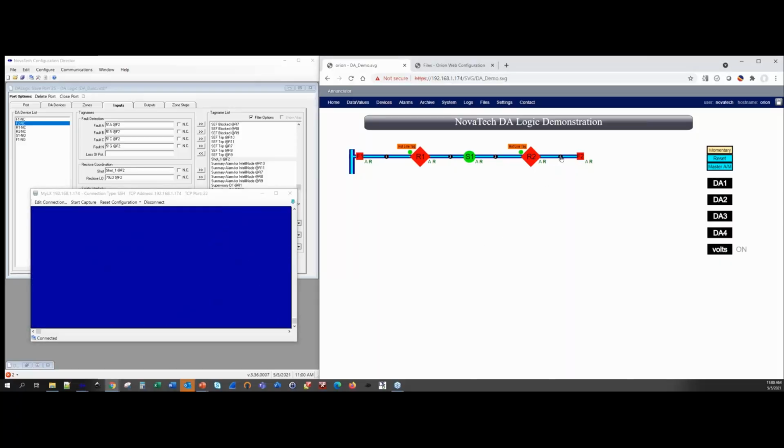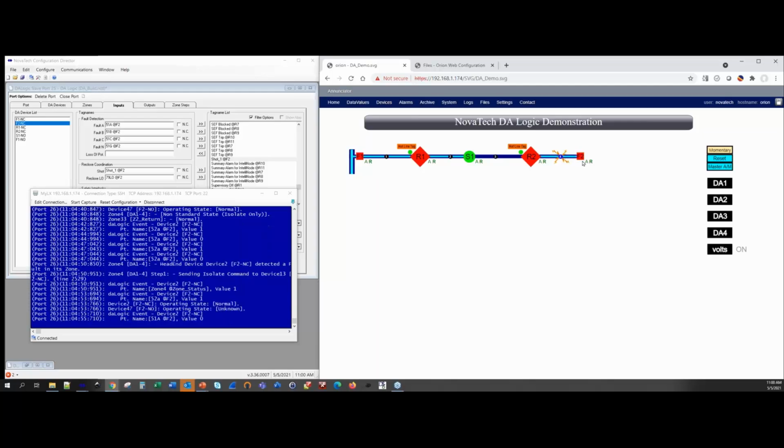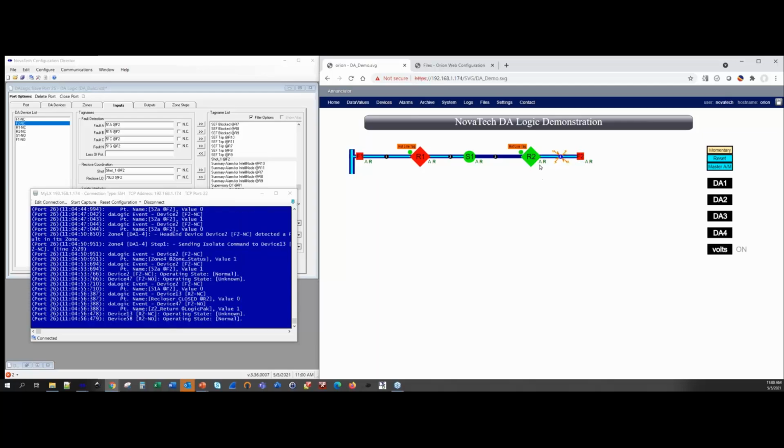And let's do that same fault over again. I'm going to initiate this test. Same kind of test that we saw before. Okay. Now we're going to see this go through its reclose cycle. And as soon as that happens, we're already identifying the fault before this goes to lockout. DA starts, opens up the recloser 2, closes at switch 1. Any second now.